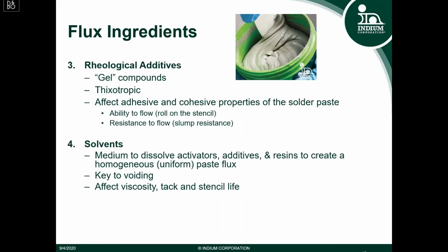The third group of chemicals in a flux chemistry are the rheological additives. These are thixotropic gel compounds that affect the viscosity and rheology of the solder paste. They make it so that the solder paste has the ability to flow well, roll well on the stencil, and are slump resistant. And then finally, the last group of chemicals are the solvents.